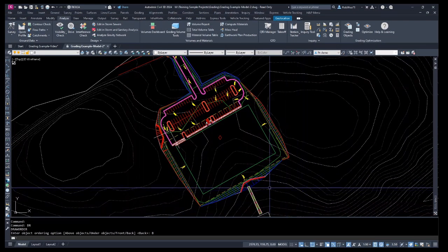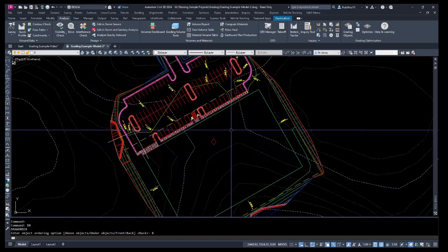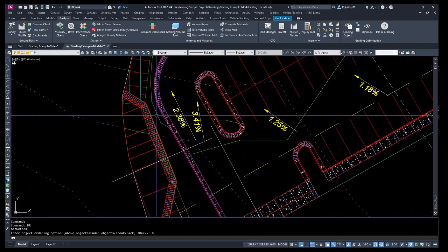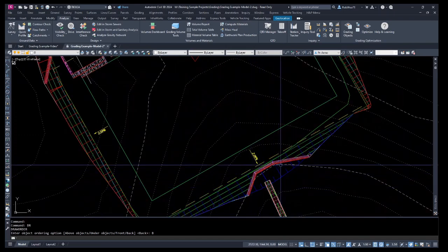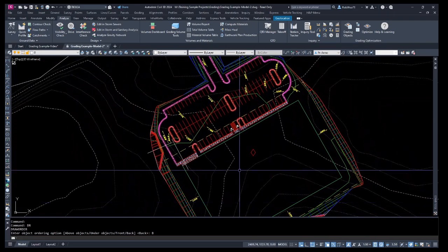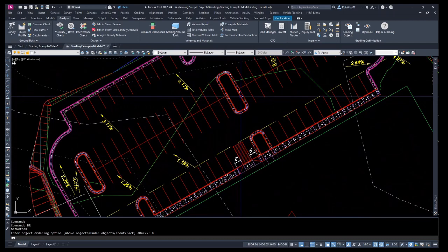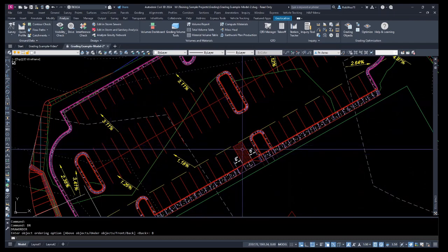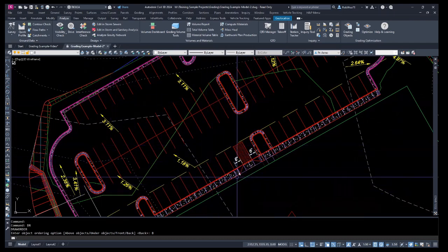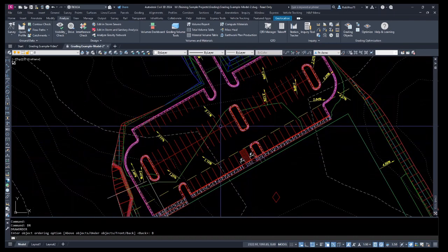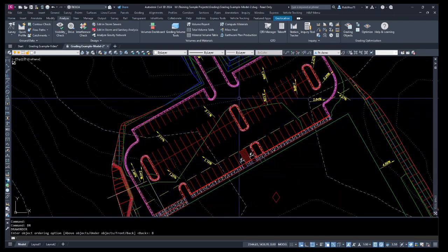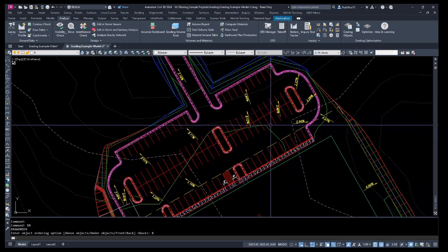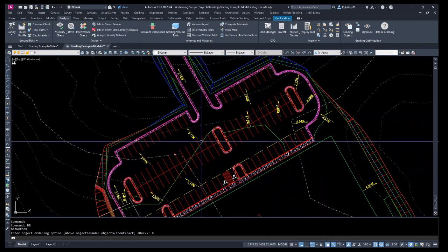So after a little bit of time, I've completed the model. I've even added in some retaining walls, and we'll look at those in the object viewer in a second, as they were built a couple of different ways. I've added in the curb and gutter and the islands, and I've even done the sidewalk with the handicap ramp. And I've got some grade labels on there just so we can see what the ground was doing. So let's look at this in the object viewer really quick.